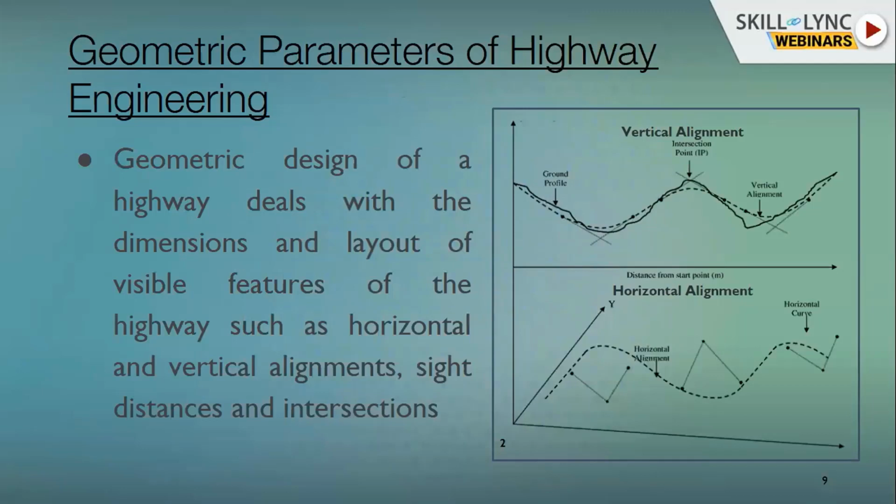So this will start the template of how the road designs will be taking forward. First and foremost will be the horizontal design, which is nothing but a collaboration of geometries, I would say, like straight, curve, transition, which is like starting from zero radius to the curve radius. So those are the geometric sections or elements we attach together to form an alignment. So it may be a straight, curve and a straight with a transition in between, or it may be a straight, curve and a transition. So it depends completely on the type of sections we are designing.